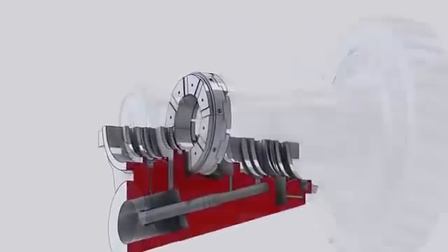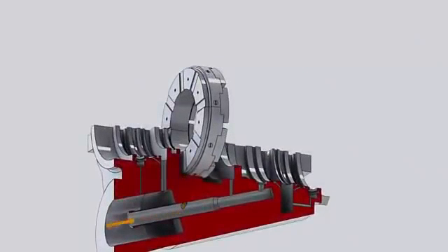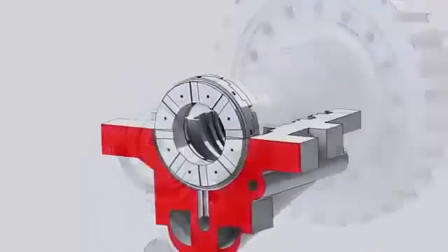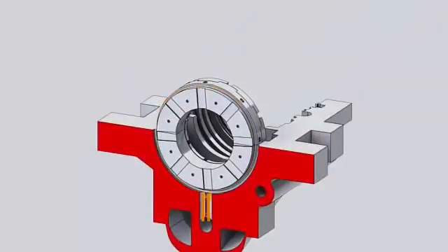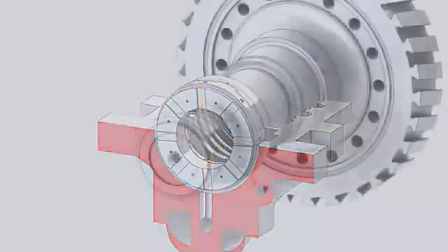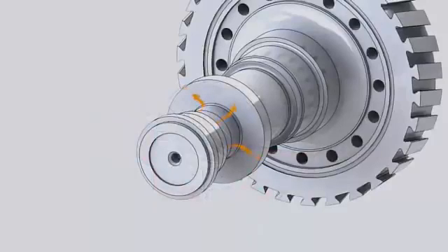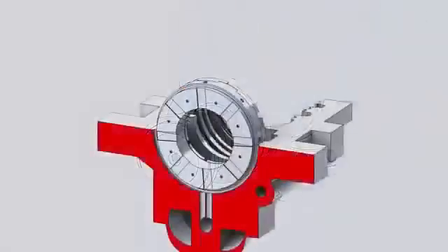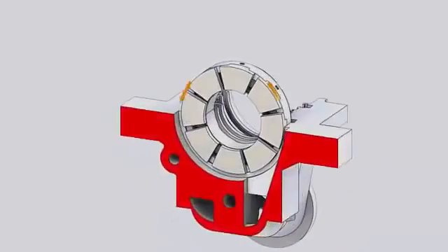For lubrication, oil is supplied through the oil feed pipe to 2 ports in the lower bearing housing, where the oil flows into the annular space around the base ring. Then, oil flows through grooves machined on the back side of the base ring to the bearing cavity, where it is carried by the pumping action of the thrust runner to the entire bearing surfaces. Oil exits at the pad's periphery to the thrust bearing drain cavity down to the lube oil drain piping.